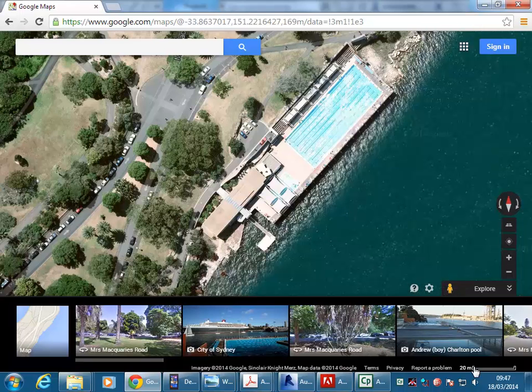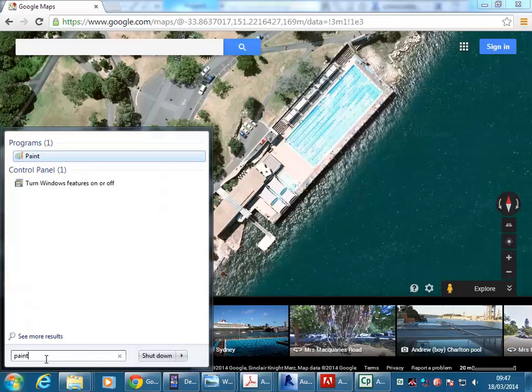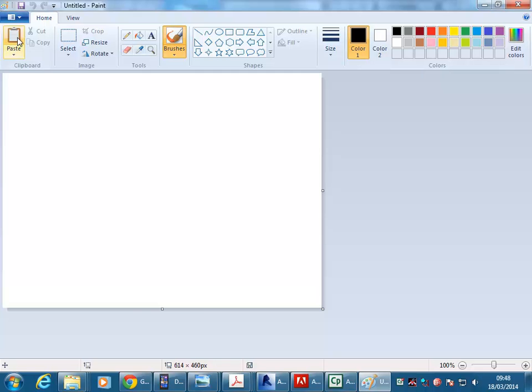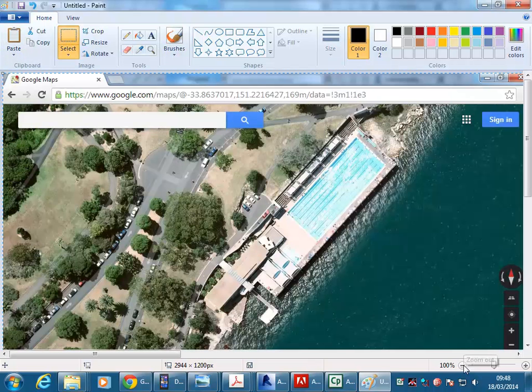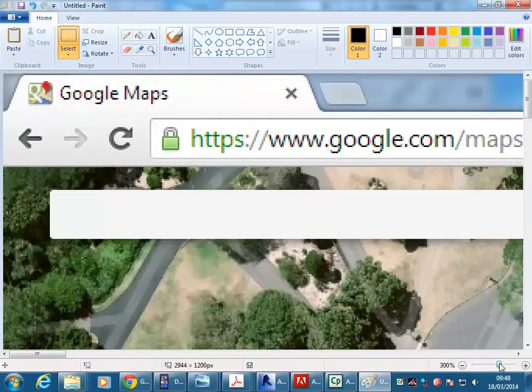So that's what I want, essentially that view. And I'm going to capture that now, just using Control Print Screen, which should get just the active window. And then a really good tool to use with screen captures is, believe it or not, Paint. Photoshop works as well, but I like to use Paint. Then you can have Paint open, use this to dump things into, and then bring them from there into Photoshop, and that works pretty well. So if I paste this in now, you can see we've got the image there, and you can zoom out if you want to, and make sure you've got everything.